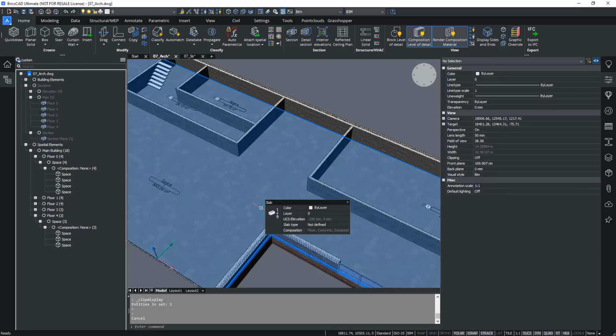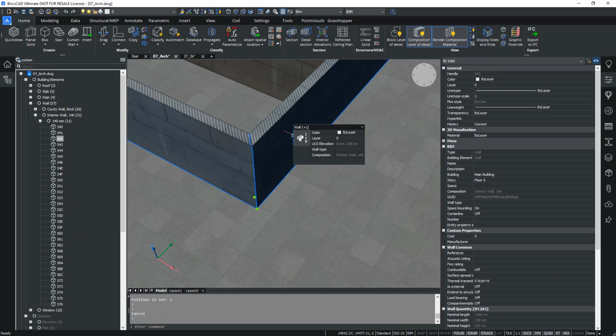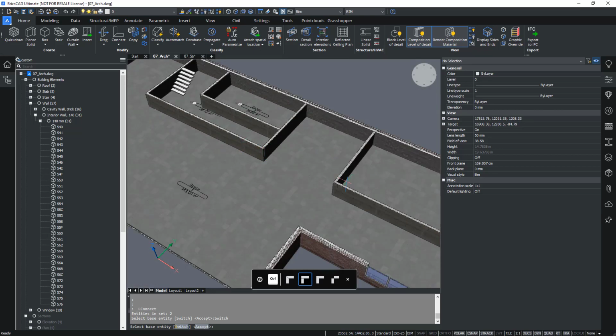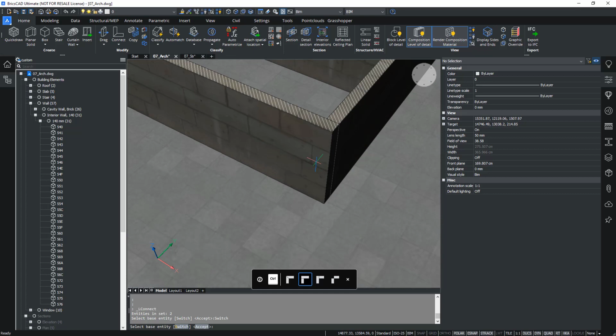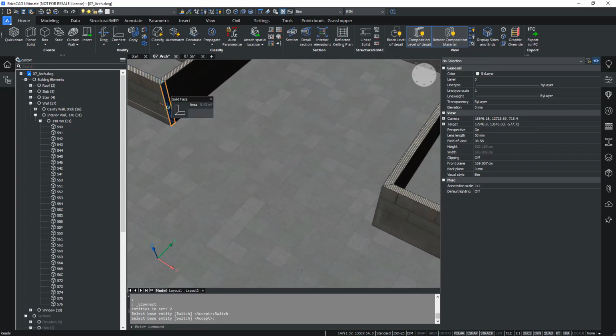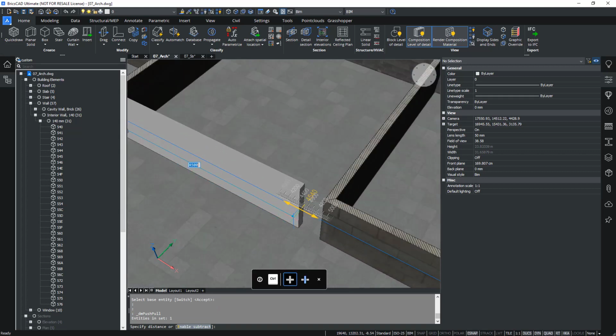Okay, as soon as we did that, I will DM push pull this face after L connecting, so that I can create a different L connection. So I want to create an L connection so that I can extend this wall to the next part. So I do enter. Then we highlight the end face of this wall, and I can DM push pull it. Make sure that here it's really disabled, the subtraction option, otherwise you will be subtracting from your solid face.